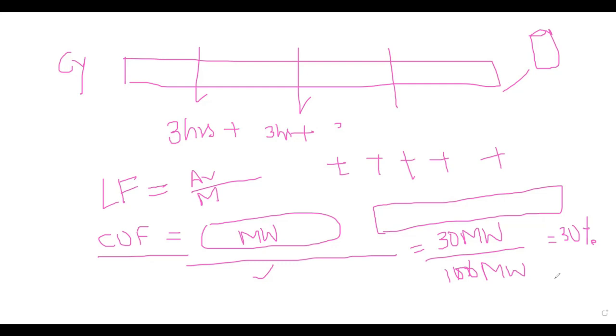And if you see the wind, the season will be June, July. In these months only you can see 90% generation, the capacity utilization factor 90% on average for June, July, August. In the rest of the months, you won't believe that from a 100 megawatt wind plant, you can get only 16 megawatt, 8 megawatt, even 6 megawatt sometimes. If you check coal, the capacity utilization factor is more because you have the raw material with you, the coal. Hydro depends upon the rainy season, the water content, again the source.